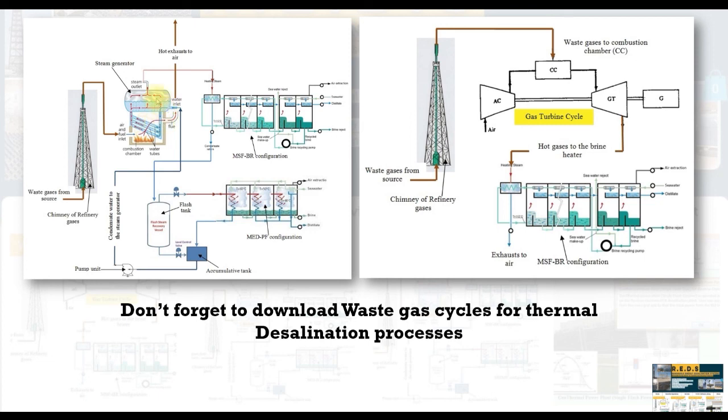And this steam generator is going to power a multi-stage flash with brine heater, and the condensed steam is going to be reflashed again to operate MED. It's a hybrid cycle, and the accumulated steam will be repumped again to the same generator.